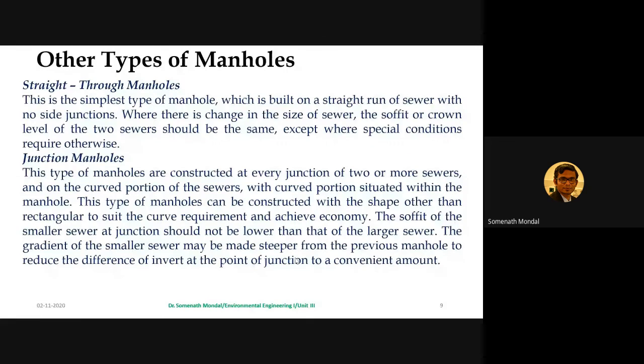Now, apart from these, we have another two types of manholes. So these are not based on depth, but we have some other different types of manholes. Let us discuss them. So we have straight through manholes. Now this is the simplest type of manhole which is built on a straight run of sewer with no side junctions.